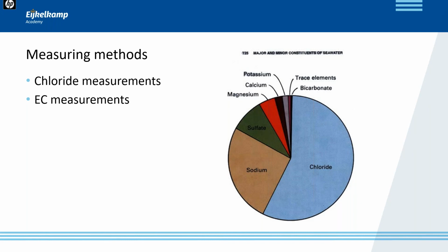The measurement of the EC value provides a good indication of salinity because when the amount of ions rises in a solution, also the EC value rises. With EC measurements, all dissolved salts in the water are measured, and not only chloride, for example. EC can be measured in the field with a simple small sensor.